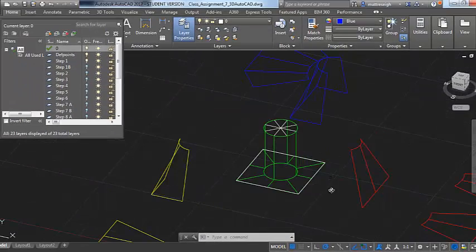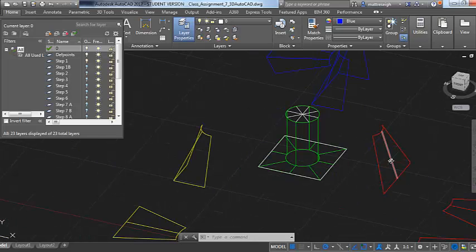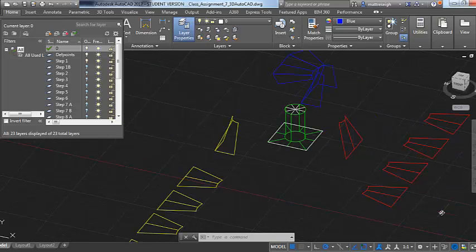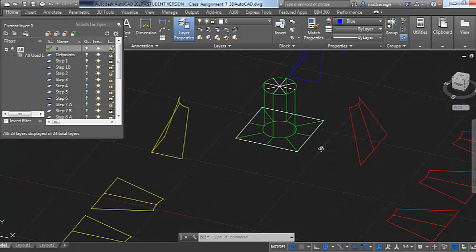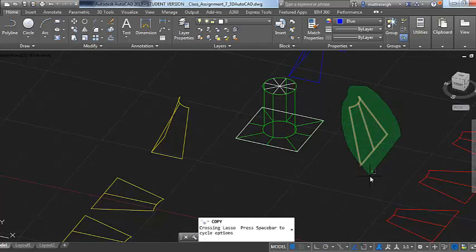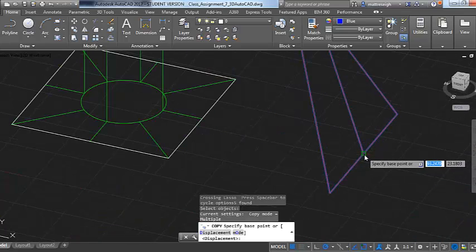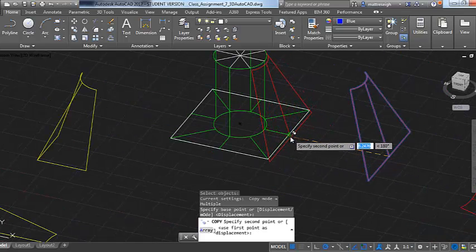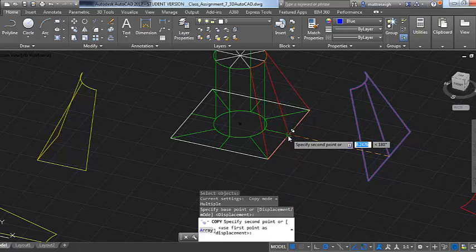So here's my preferred way to do it. This red group of patterns is what I've developed, and I would need 4 of those to make my squared around with this particular weld seam pattern. I'm going to copy this particular part here by its base, and I'm going to show you. This piece ends up being the 8 inches on the square side, and then it matches up to where it meets my 4-inch round, 6.5 inches tall.